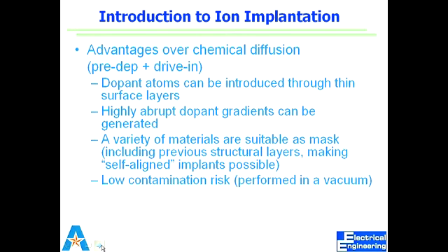I guess what we're asking is, does this avoid the bird's beak? Bird's beak is not a function of doping, is it? No, not a function of doping, but you're concerned about lateral straggle, or the lateral travel of ions. Yeah. But in this case, could this be applied to the silicon dioxide method? It does not apply there.